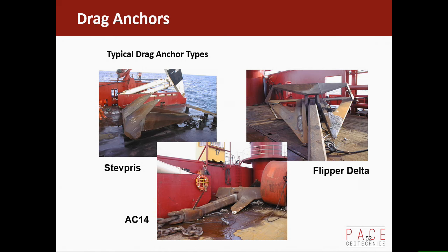And by doing that, in a soft clay, the clay is getting stronger as you go deeper, and in the sand, it's gaining its strength from the friction, the overburden pressure, so it's getting much stiffer. An AC14 is really more designed for harder soils. It's not really designed so much to penetrate deeply. You can see the palm there is much heavier. Those are like that to try and penetrate into sand rather than skid over the top of sand.